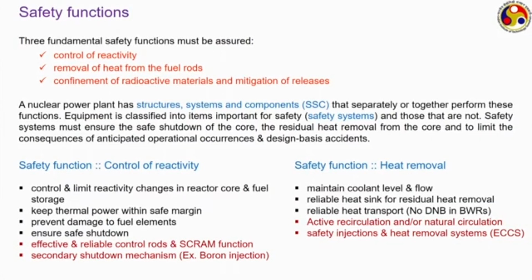Because there was no power available, the coolant recirculation pump stopped working, and so no coolant was flowing through the reactor core. Despite all the effort, the reactor core continued to produce decay heat, and they were not able to arrange any additional power. They had backup diesel generators, but unfortunately, because of the tsunami, those also went underwater, and they were not able to start the pump.